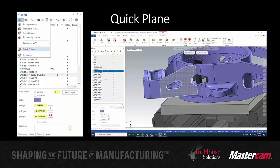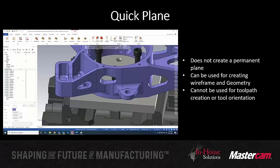Okay, so another new feature is Quick Plane. So when you're sketching out simple features or holes on a part and you don't want to necessarily create a whole new plane for this, you now have a new Quick Plane option, which allows you to create a plane off of a solid face temporarily for basically drafting purposes. The plane will not be saved. So, Andrew, if you could move to the next slide. So basically, by clicking on any face, it's going to create a plane on that face. However, it's not actually going to save that plane. It can be used for creating wireframe and geometry. It cannot be used for toolpath creation or tool orientation.